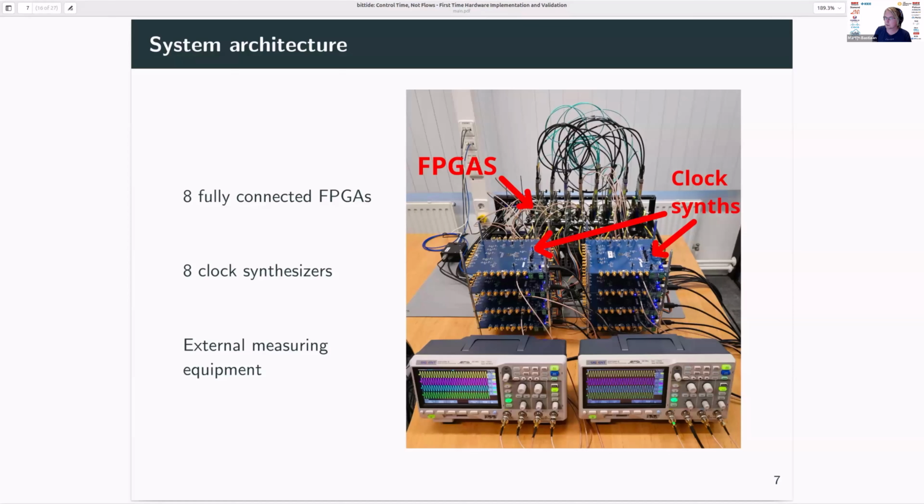So, as the name implies, of a clock synthesizer, these parts can generate clock signals. In our specific case, a reference oscillator is part of the board, and it's wired to a PLL. This PLL can convert the reference frequency, whatever it may be, to basically any frequency you'd like, somewhere between 100 hertz and 700 megahertz.